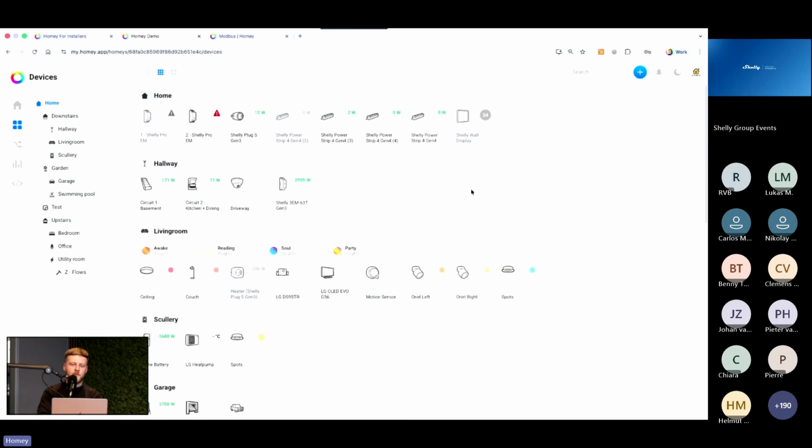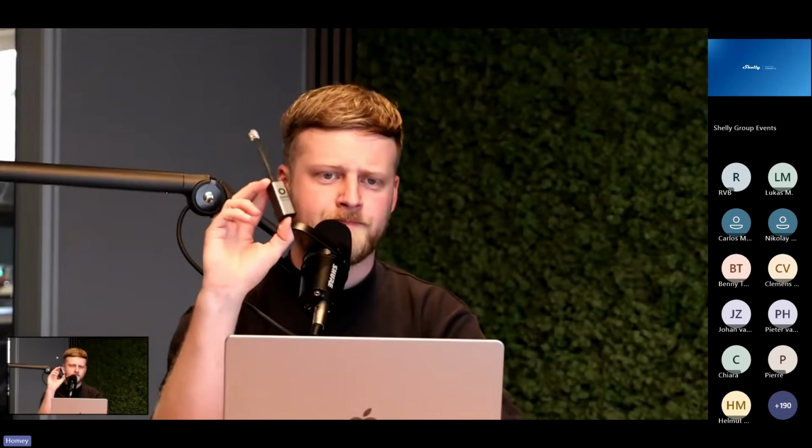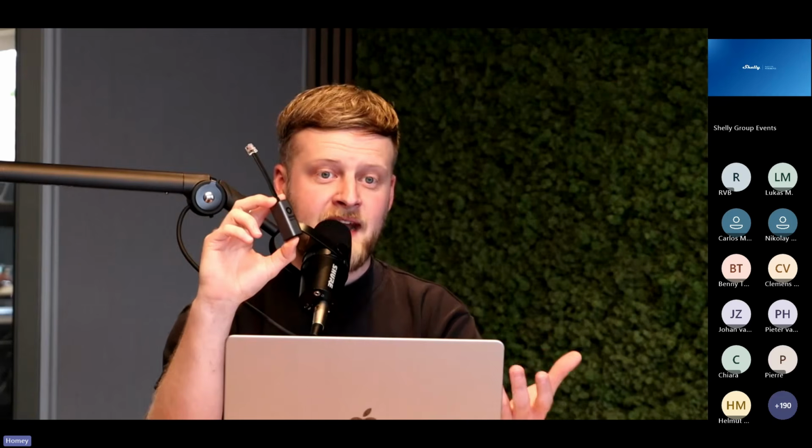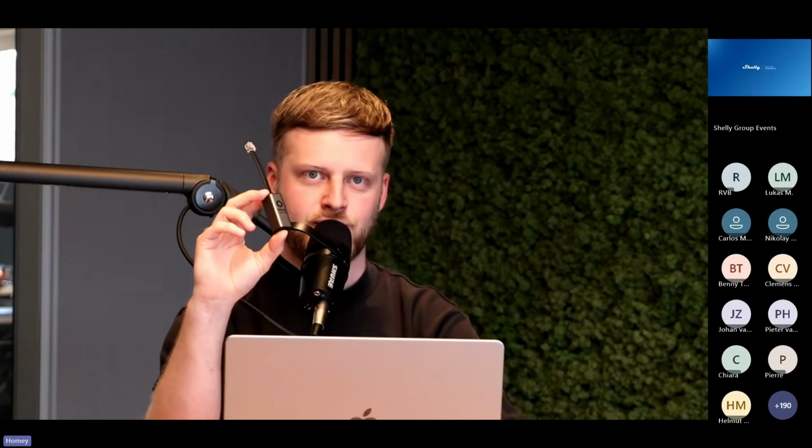Of course, first, what you can always do in case the end user has a smart meter in their home, you can install, for example, the Homey Energy dongle. This is a P1 enabled energy dongle that just plugs right into the user's smart meter to get the data. So we'll get the data from the whole household, but when you're delivering back to the grid, that way you can also see how much PV you have available to manage within the home. But then again, if the customer doesn't have a connected inverter or a smart meter, which is the case in a lot of households, Shelly also offers some great products.